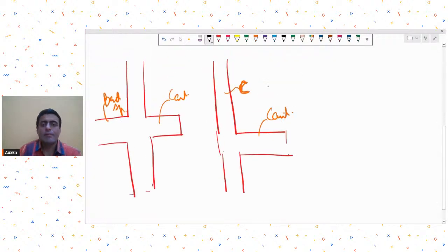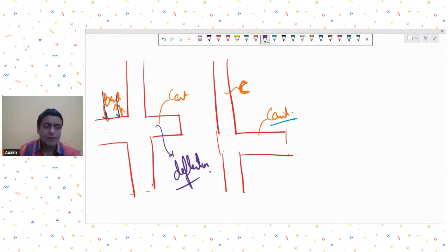I don't know. Anyway, since I have drawn this image, let me tell you that these cantilevers which do not have backspan are slightly more challenging, so to say, than the cantilevers which have backspans. Why so? Because of the backspan, your deflection is controlled. I don't know how many of you have observed. Deflection in the cantilever is reduced when you have a backspan, and when you are able to load your backspan, you will observe that the tip deflection in the cantilever will decrease. How many of you have observed it? No one?